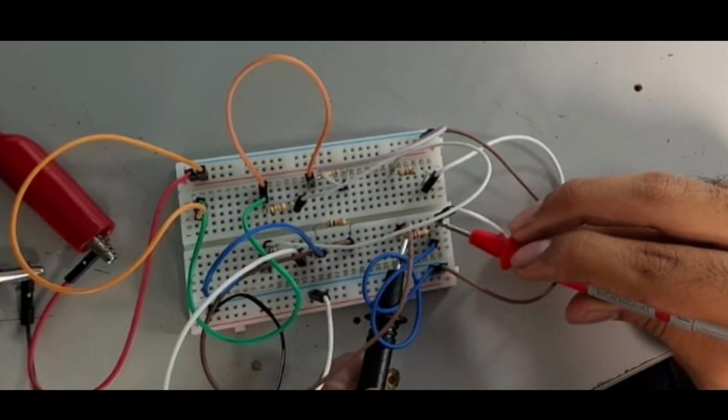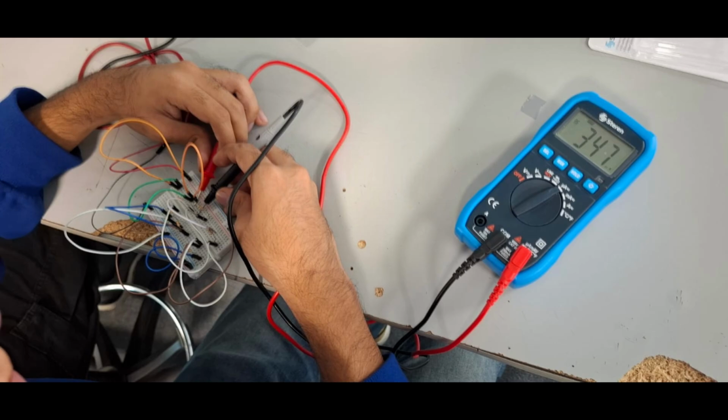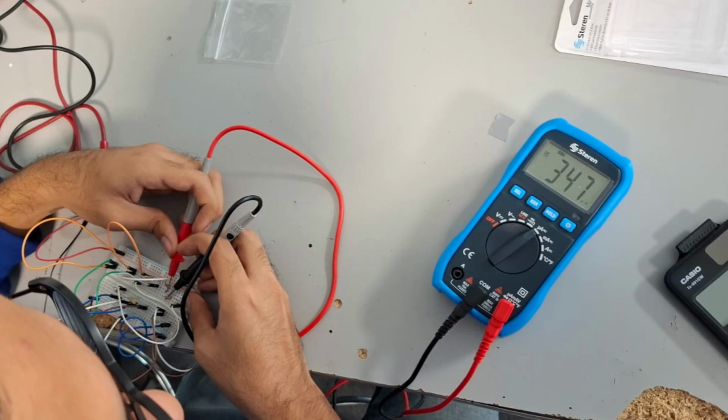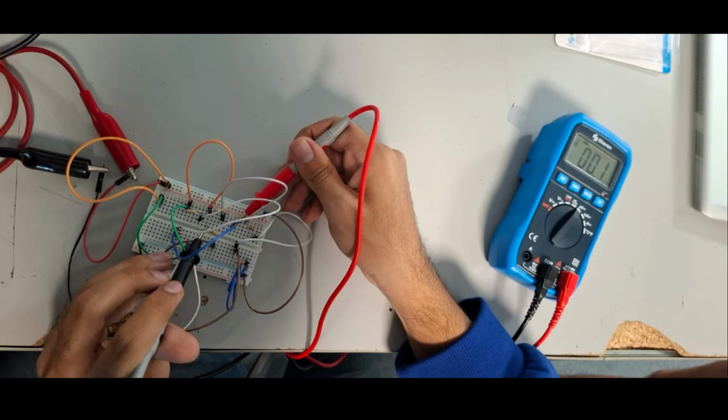I will explain the implementation of the circuits on the protoboard and the process of measuring the voltage and currents in each electrical component. To begin, we assemble the circuit on the protoboard following the exact same connections as in the theoretical analysis. We check the orientation of the power supply, the placement of the resistors, and the wiring to avoid short circuits or incorrect connections.